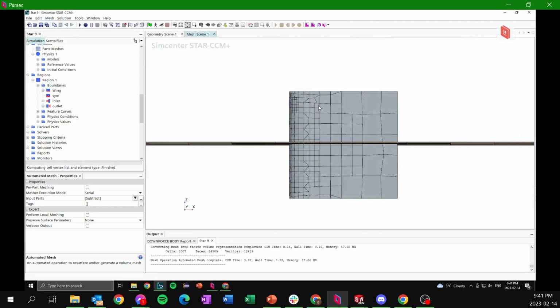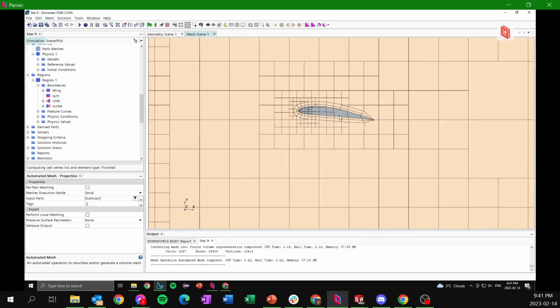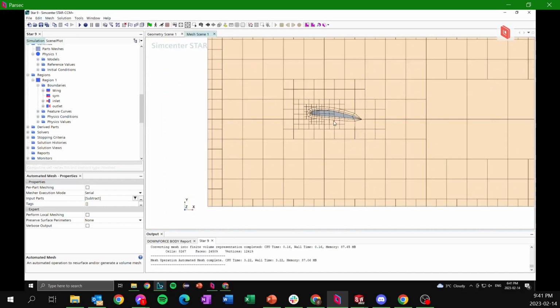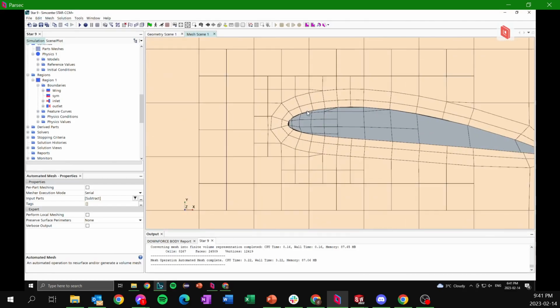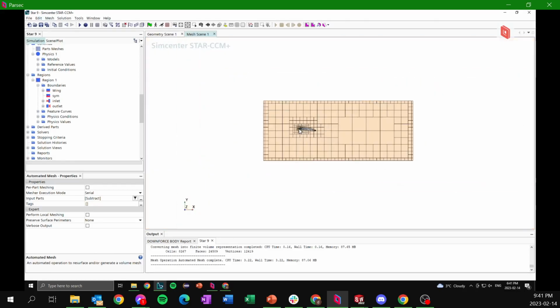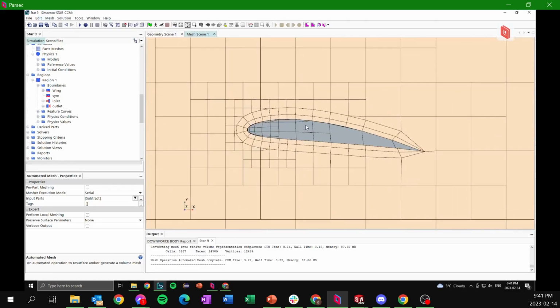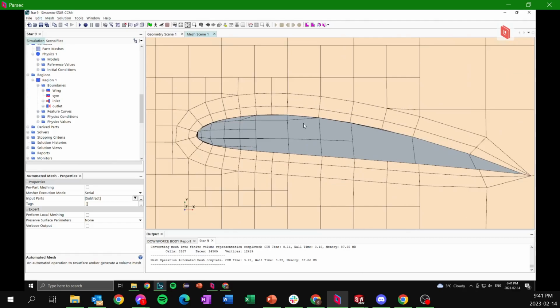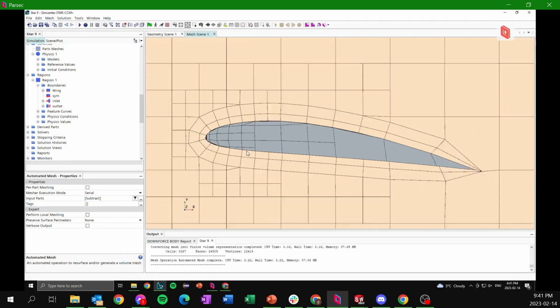Okay. People on UW Formula Motorsport, if you have worked on the mesh, is this a good mesh? No? Okay, why? It's very coarse. You're not defining multiple regions where you care less about the far away parts. It's just as fine as closer to the wing where there's going to be more interesting stuff. And it's too coarse, especially close to the wing.